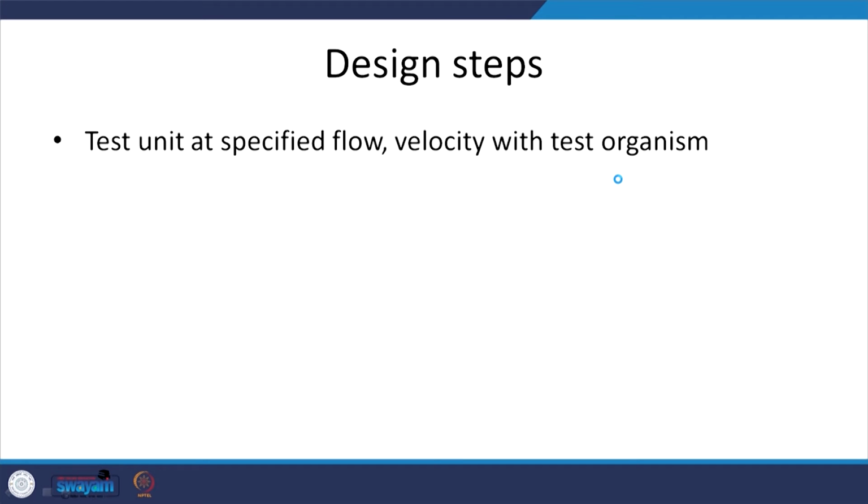Design steps. So you are going to test the unit at specified flow and velocity with test organism. One aspect to note is that, models are fine, but when you build the system, you are going to have considerable short circuiting. So water that has to spend a certain amount of time would not probably spend as much time in that particular system.